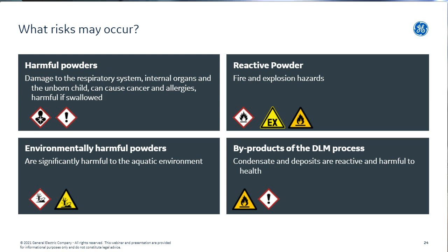That means their chemical properties create hazards for the health of people who get exposed to them, either by inhaling, skin contact, or accidentally eating them. The other very important part is the reactivity of the powders. Are they able to create a combustible dust scenario or not? Are they explosive from that point of view?